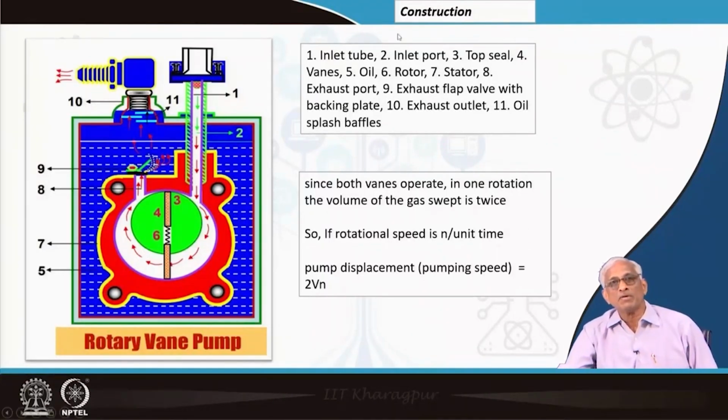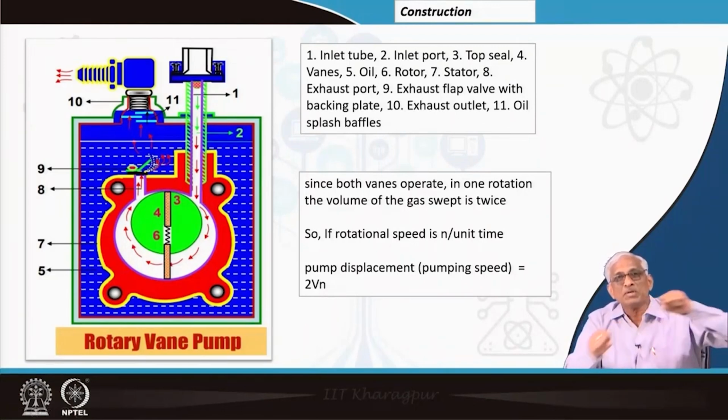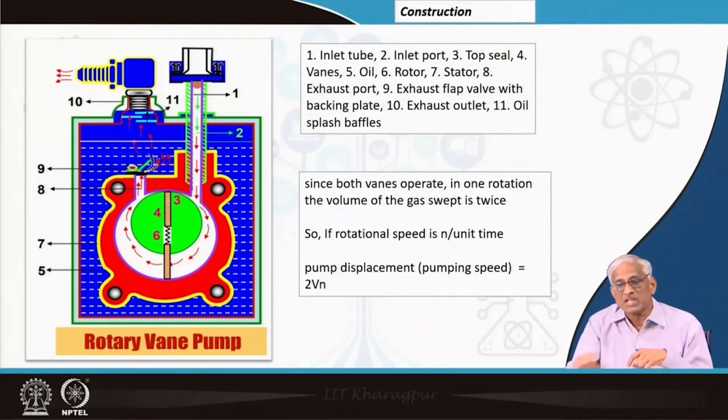That is why it is called rotary vane pump. If you look at that vane, I hope my cursor is able to go there, yeah, this is the vane. There is another vane. These two vanes are supported by a spring, so that centrifugal force plus this force will try to keep these vanes always touching the inner lining of another